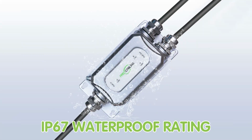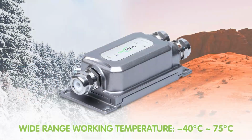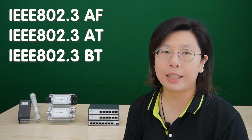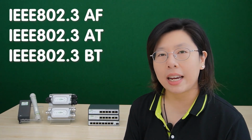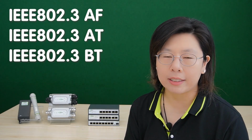It is IP67 waterproof rated and also has aluminum IK10 vandal proof and a wide working temperature range from -40 degrees up to 75 degrees, which is ideal to resist outdoor harsh environment. It is compatible with IEEE 802.3 AF, AT, and BT standard, provides 60 watts of power maximum, and also serves PoE PTZ cameras and Wi-Fi 6 stations perfectly.